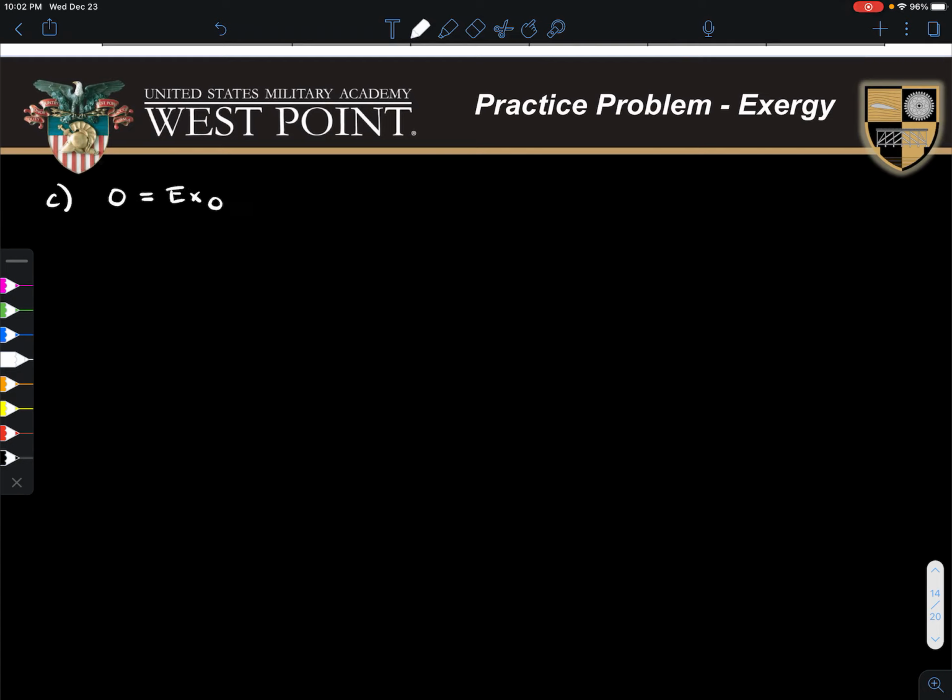So an exergy balance, first for rate terms, we start out with the rate of exergy associated with heat transfer. Then the rate of exergy associated with work, the rate of exergy flowing into the system, and, oops, I should add a plus sign there, the rate of exergy flowing out of the system, and then last, an exergy destruction term.